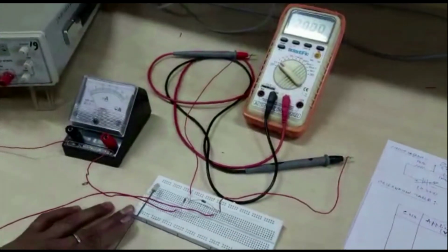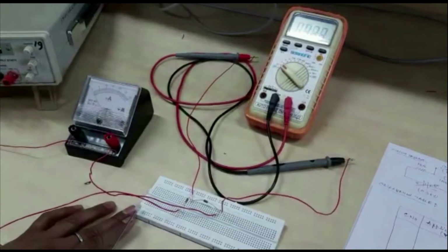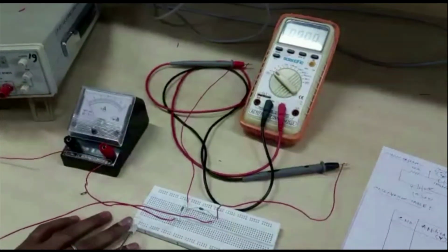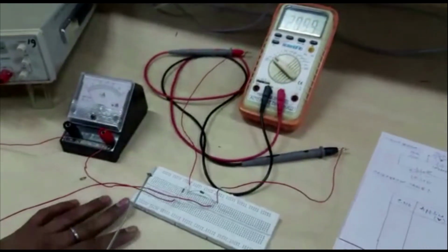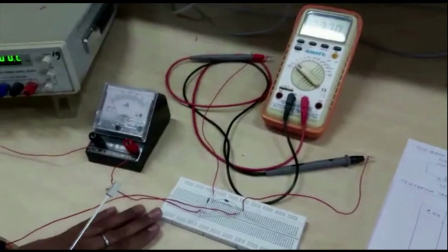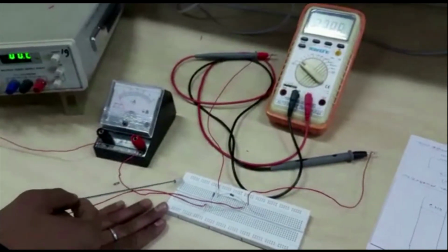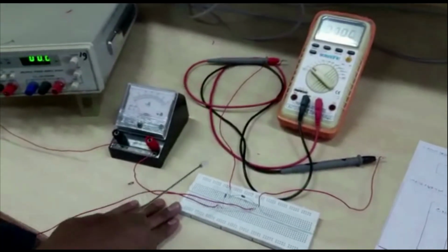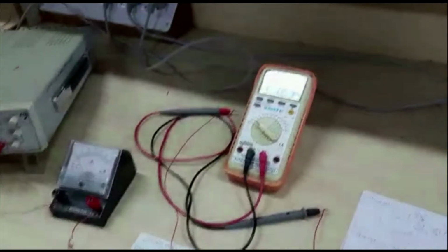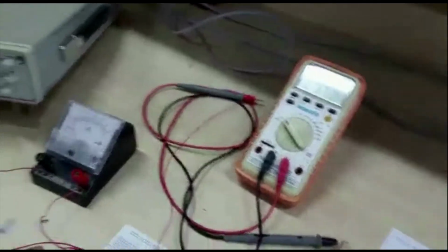Now these are different holes. These are called 5-hole nodes. Each set of 5 holes is shorted on the back side. So when we want to connect different wires or terminals of the components together, we will put them in points of these lines that will be shorted. Similarly, there are different sets 1, 2, 3 and so on. In the lower section also, there are different sections of 5-hole nodes.